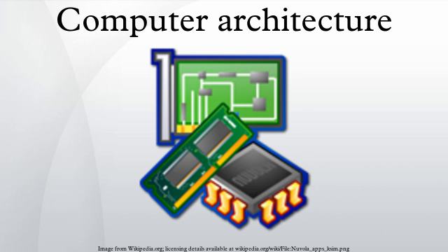This measures the efficiency of the architecture at any clock speed. Since a faster clock can make a faster computer, this is a useful, widely applicable measurement. Historic computers had MIPS per megahertz as low as 0.1. Simple modern processors easily reach near 1. Superscalar processors may reach 3 to 5 by executing several instructions per clock cycle.